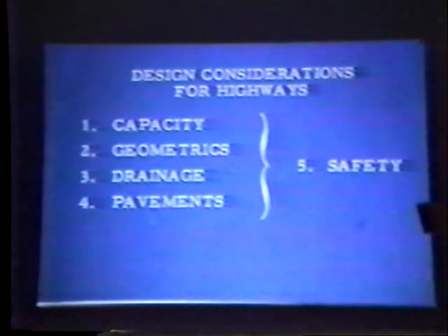The geometrics or the design, both in terms of vertical alignment and horizontal alignment, are extremely important and can make the difference between whether a road is safe or not. And there are some associated aspects of geometrics that we'll talk about as well. The film that we just saw made the point that drainage is extremely important. I remember a saying from many years ago that the three most important aspects of road engineering are drainage, drainage, and drainage.